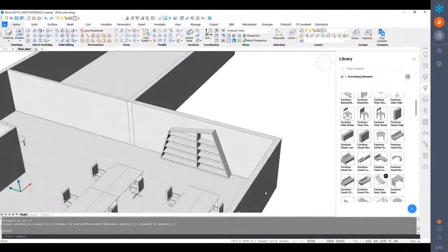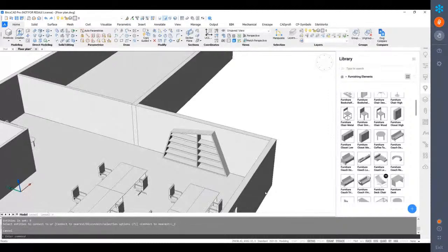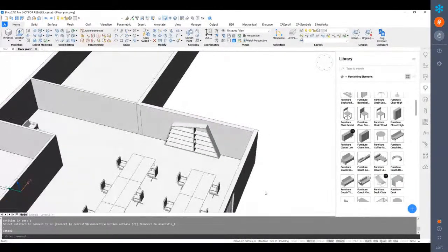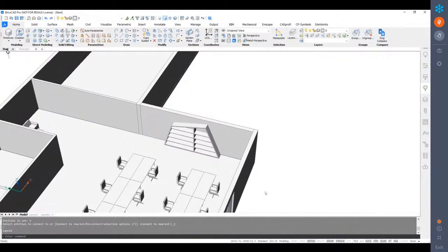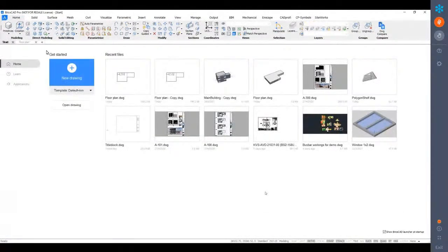And beyond this, we can actually add this into our library. So that's another thing that's really good. At this point, I'll just create a new drawing. And I'm just going to use a new drawing to make sure that I'm on a 0, 0 starting point whenever I insert this component in. So that's something that you don't really need to do. You can actually add this component into the library within a whole model, but it's just something that I like to do because it's pretty useful.